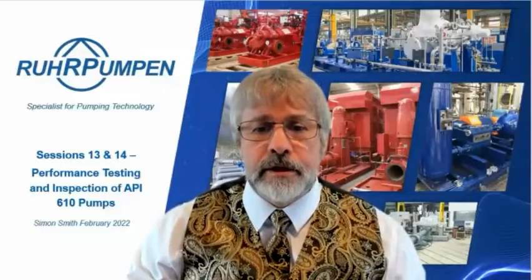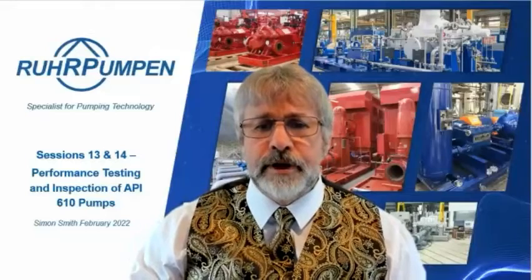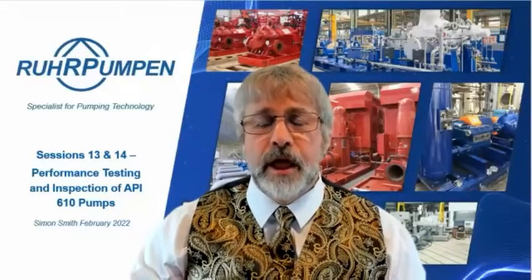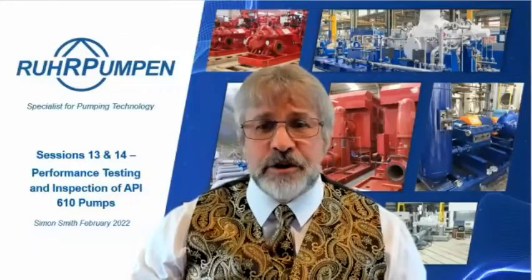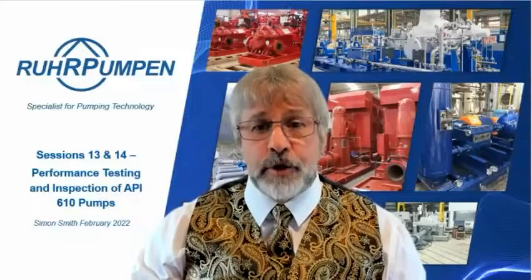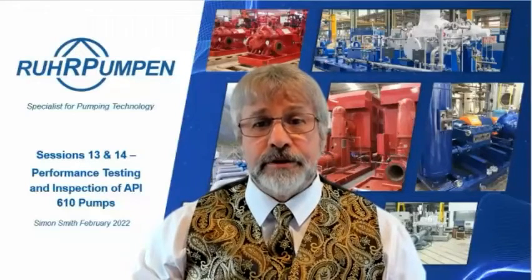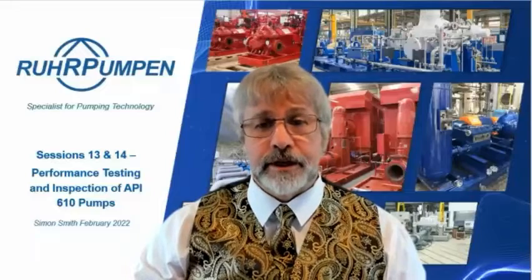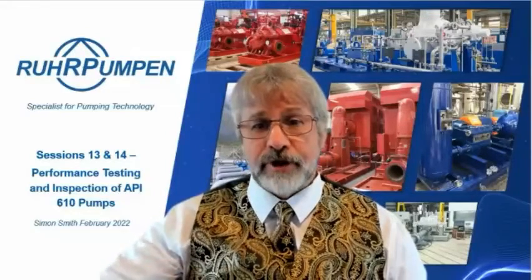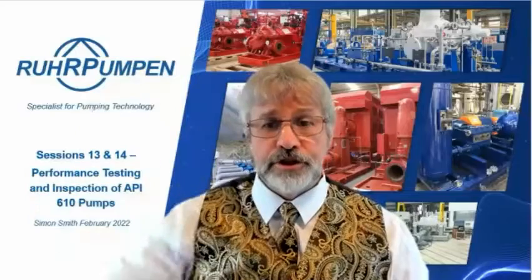John Lester, is the setting of your pump lift affecting the performance of the pump? So that would be on a vertical pump installed in a pit. Yes, you would just take into account the suction lift when you calculated your overall head. But yes, it would impact it. You do need to consider the lift from the water level in the sump up to the discharge level.